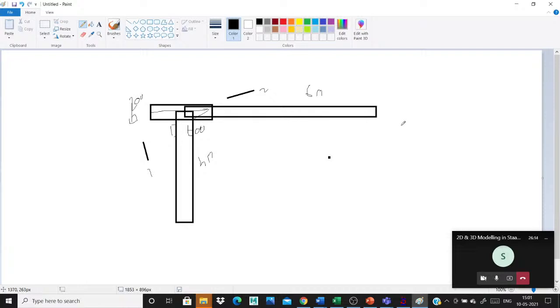Which side will be applied for the beam's column depth? The column depth orientation is toward the longer beam side. Okay, this is the correct one. You apply your orientation based on the longer beam and also the load condition, for your orientation of the column.